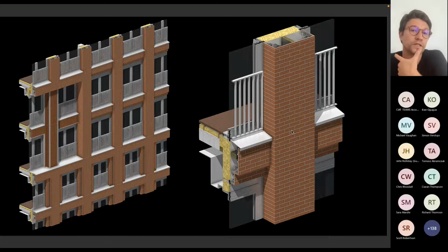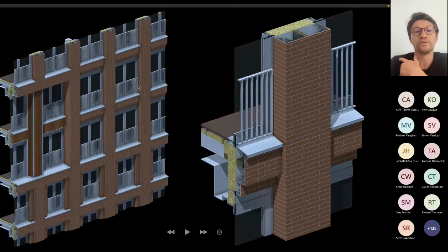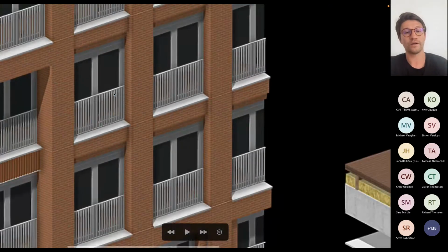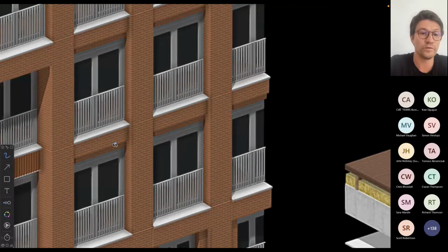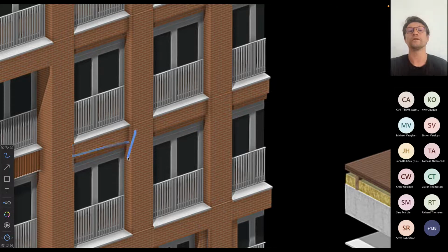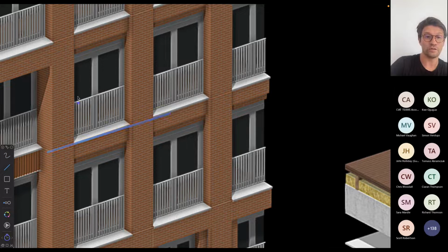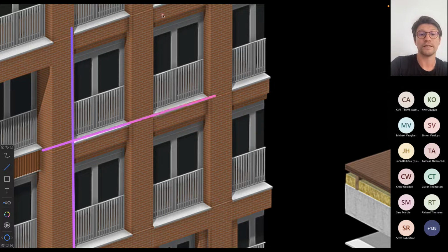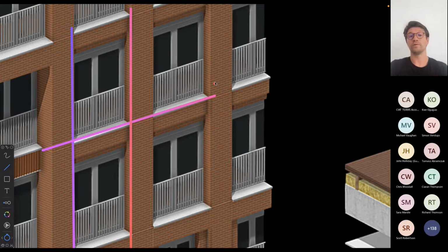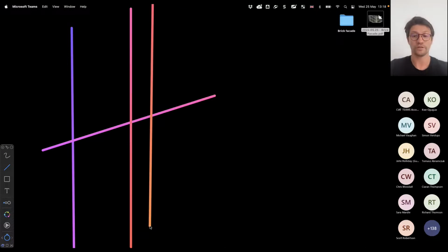There are two restrictions here. First, we are going to have a lot of joints because units are usually, to have them cost effective, no more than, let's say, 2.5 meters wide, and they would have to go floor to floor. So we are going to have definitely a lot of visible joints for a unitized assembly. These joints would be very visible. So that's one of the things to consider.